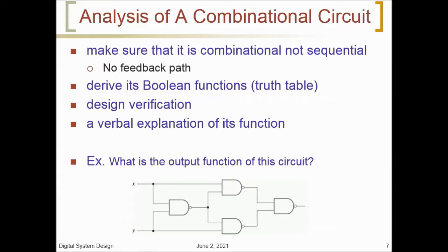Label all gate outputs that are a function of input variables with arbitrary symbols but with meaningful names. Determine the Boolean function for each gate output.